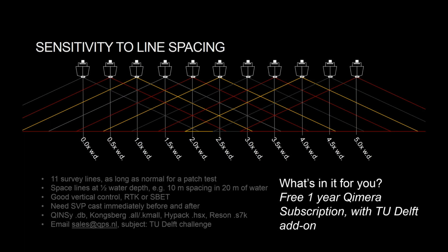So let's say it's 100 pings along a survey line, and you grab the equivalent number of pings to the port and starboard lines, and you solve for the value. And it's the granularity of that window size that lets you resolve quickly varying oceanographic conditions. So it is, by design, purposely built to handle that exact scenario. If we expose more of the parameters of the algorithm and let you choose something like a single harmonic sound speed per line, then that wouldn't handle that. But by design, it's chunking it up and proceeding through the data set like that. So naturally, the outcome is handling that.